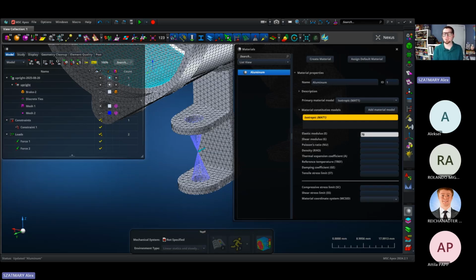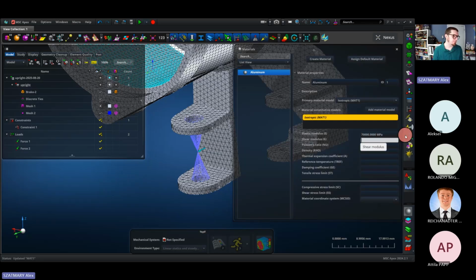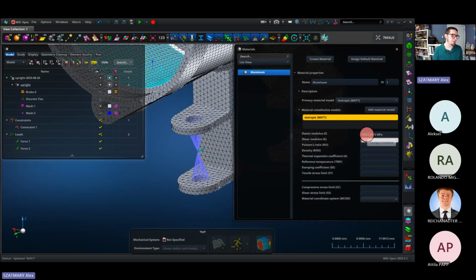And I'm using units, I should say, of megapascals, millimeters, kilograms, and newtons. So our stress unit, again, is megapascal. I want an E of 70 gigapascal, so I can type 70E3, and that will convert it to gigapascals, instead of me having to type in all those zeros.